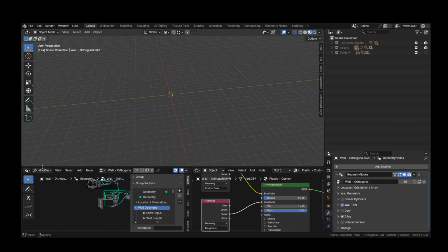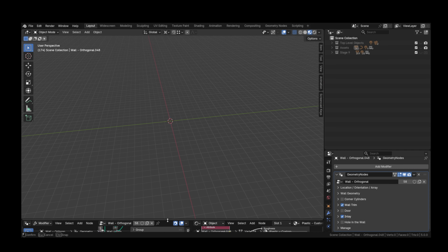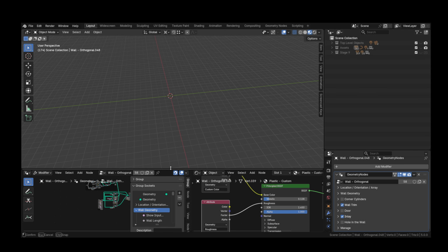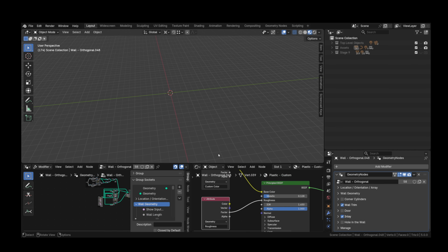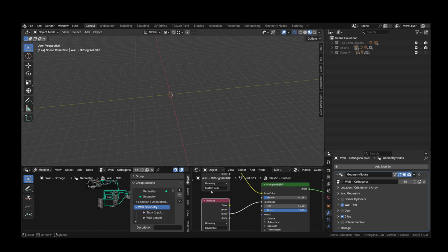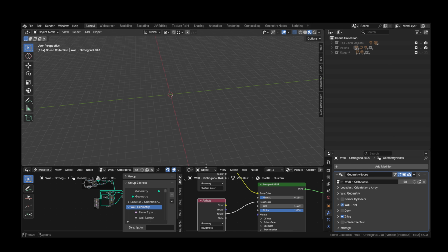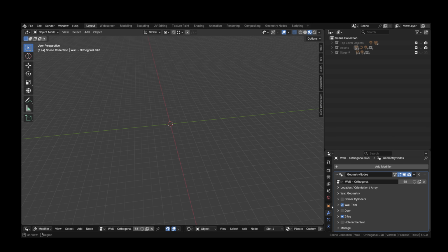If you see the border of the 3D viewport, you hover over that horizontal border until you get that white double arrow, and then you can just bring all of that stuff straight down. If you want to bring it back up, you can do that. This is true of each of the sub-windows in Blender. So you see we have one sub-window here, actually that contains two. We have a vertical border that we can slide back and forth. I just want to get that out of your way.